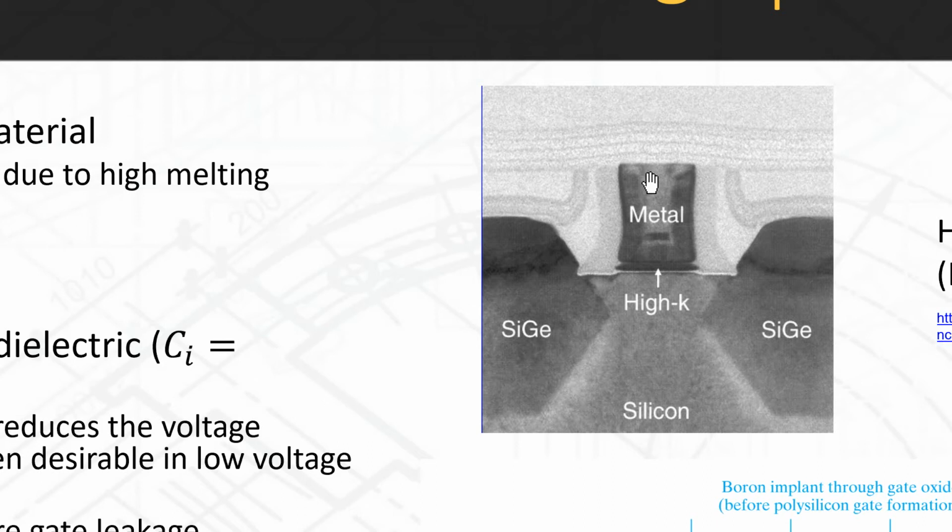So you deposit a metal layer, you pattern it, you deposit an insulating layer on top of it, because you can't have 2 metal layers touching each other, right? So it's alternating. These different layers, I'm guessing, are different layers of metallization and insulators. And then did they just plop a metal on top? Because it looks like it was 3D printed essentially. I'm guessing if you use gas deposition, it would permeate into the substrate. So how did they get that metal piece to sit on that dielectric?